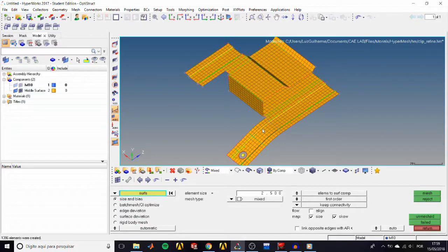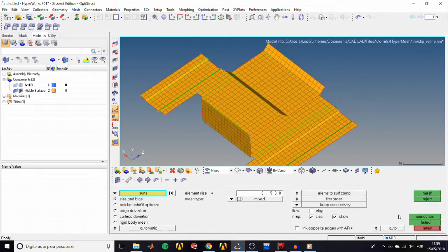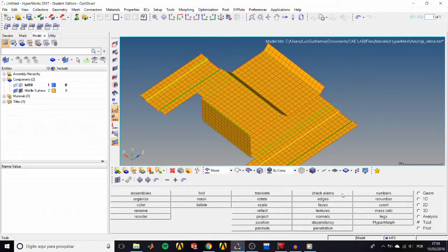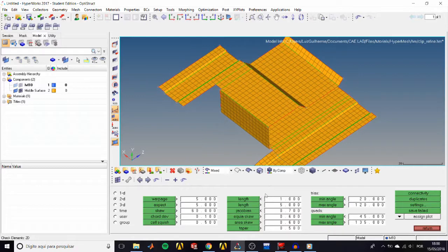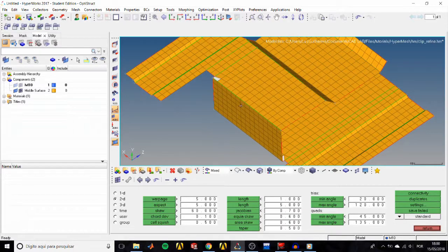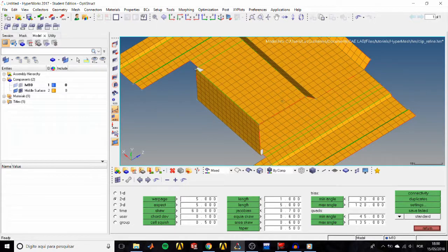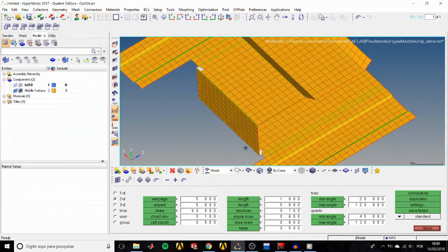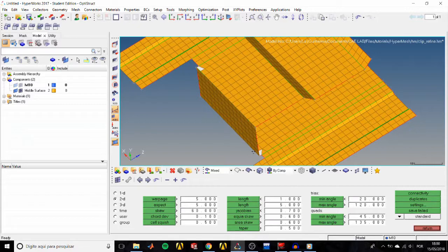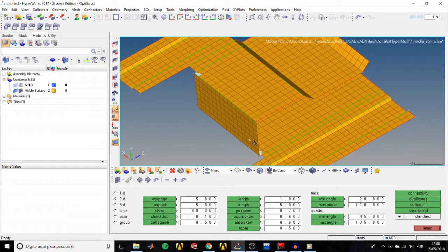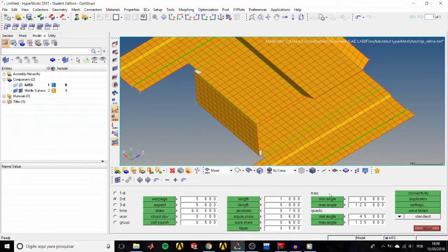Now check the New Mesh in the Tool page. Check Elements panel. Click on Length again. Now we see that only these 2 fail since we haven't dealt with these 2 notches. I'll leave for you guys to try to refine that. So let's remesh it using a new function.